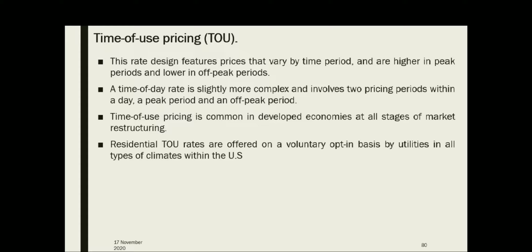But in actual dynamic pricing, one of the important variants is time of use pricing or time of use tariff. These are pre-declared tariffs varying during different times of the day, that is high during the peak hours and low during the off-peak hours.